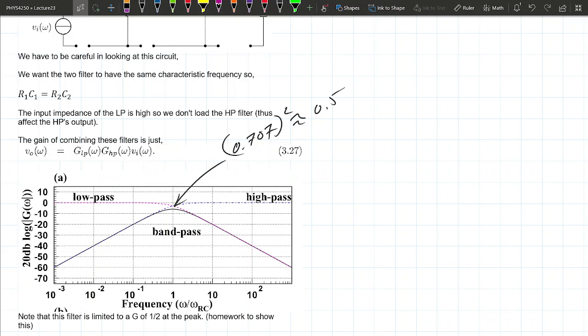A lot of times if the gain is not a big issue, and we're going to see that usually it is not, because the next thing we're going to cover is semiconductors, and the one after that is going to be amplifiers, you can always amplify the signal. And usually this is a more cost-effective way to make things rather than putting in an inductor, which A, costs more, and B, drains more power. And that's what most people use instead of using inductors.